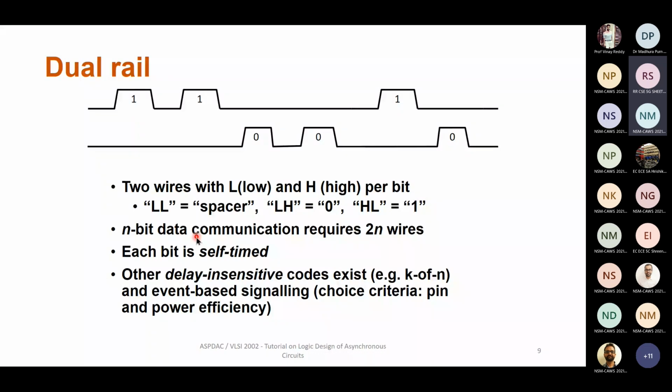and all F's, all ones added with all ones, is going to take the maximum time if it's a simple ripple carry or any similar adder. In a synchronous design, we would always give the delay to the adder based on the max delay, which is all ones being added together. Whereas in an asynchronous design, the timing gets decided based on the data.